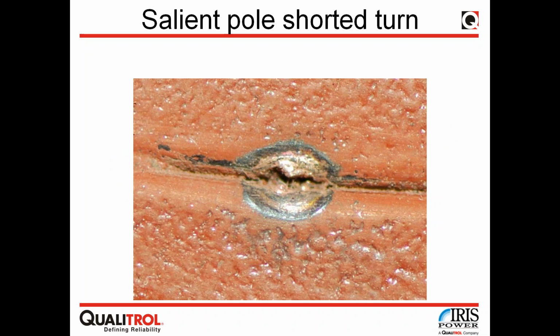We do have hazardous location certificates for the flux probe, so the flux probe itself can be installed in a hazardous rated motor. The signal that comes from a flux probe is relatively low frequency, so it can be led with wires up to 150 meters long. So there is no reason for a box to be within the EX1 zone, at least.